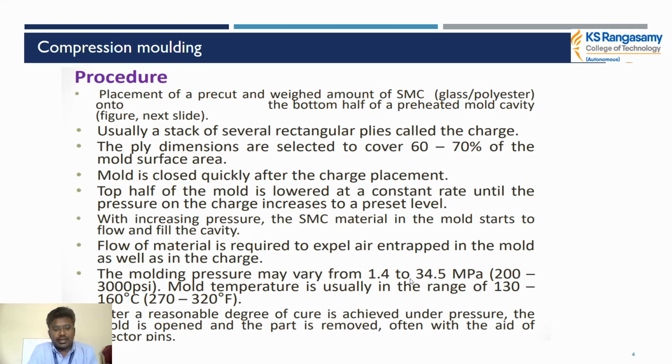After a reasonable degree of cure is achieved under the pressure, the mold is opened and the part is removed with the aid of the ejector pin. So this is the major procedure we have to follow in compression molding.